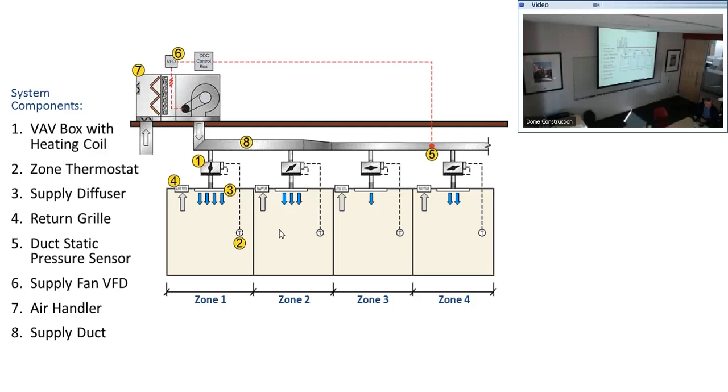That water will drain into a pan inside the unit. That water needs to be taken away to sanitary, not storm, drain piping on the roof. And that's city by city. And assuming that it's on the roof, if it's a split system, take it to sanitary. Don't let anybody tell you can just dump it onto the drain and send it down the storm. They don't allow it.